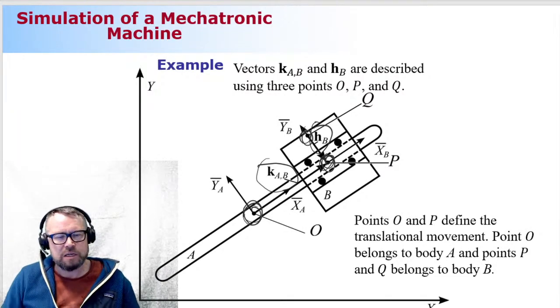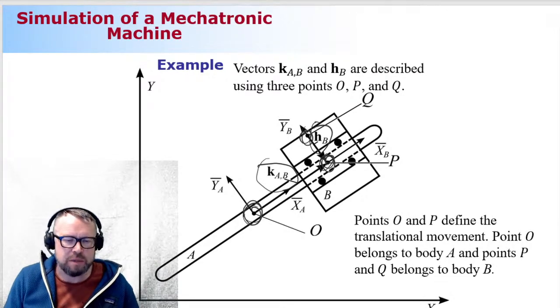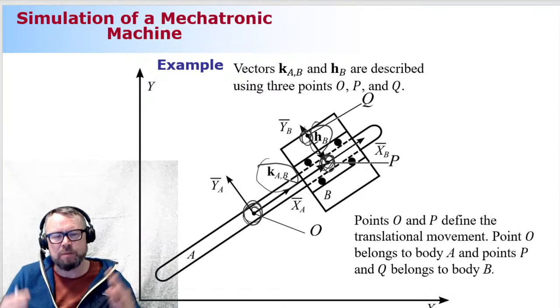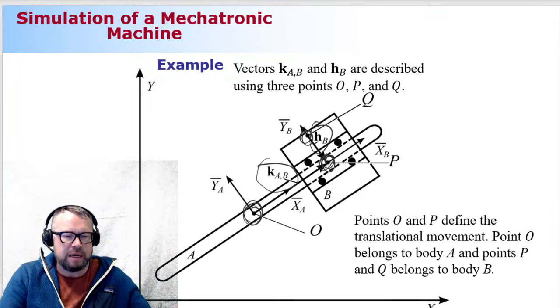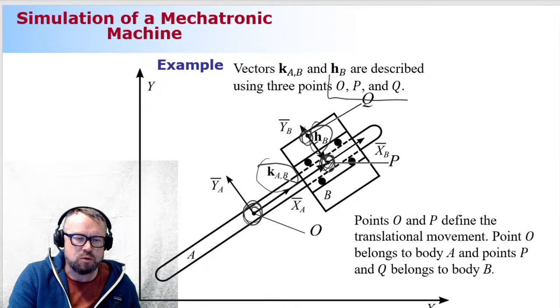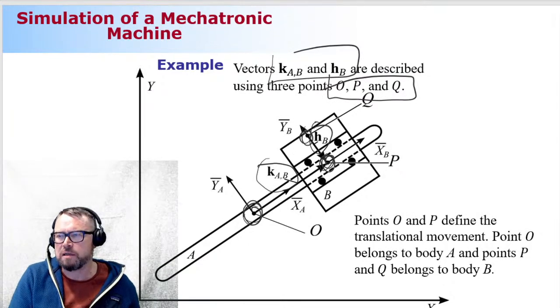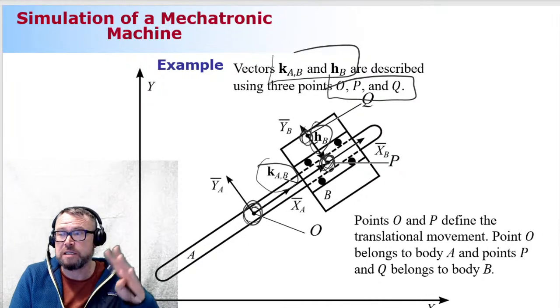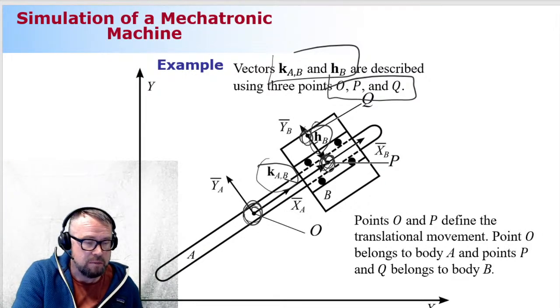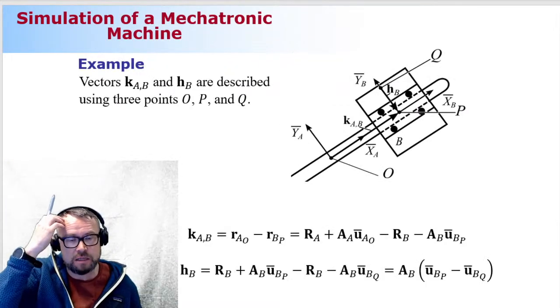So that's a sliding constraint. Sorry that I'm a bit unclear in this matter, but end of the day, what matters is that you're selecting these 3 points, you're selecting these 2 vectors correspondingly, and that's it. And then you just set this perpendicular condition. Perpendicular condition we're going to take a look at in a second.